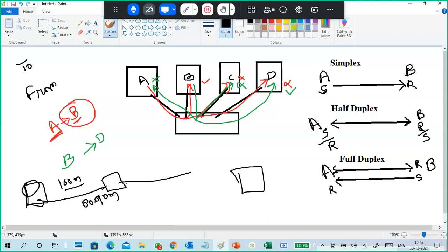Then I run another cable from here. I connect this cable to the hub and the hub to the outside, so I can run up to another 100 meters, like 80 to 90 meters, and use the cable and a hub again like that. If the required cable length is more, it leads to signal degradation, so we have to use a hub as a repeater.